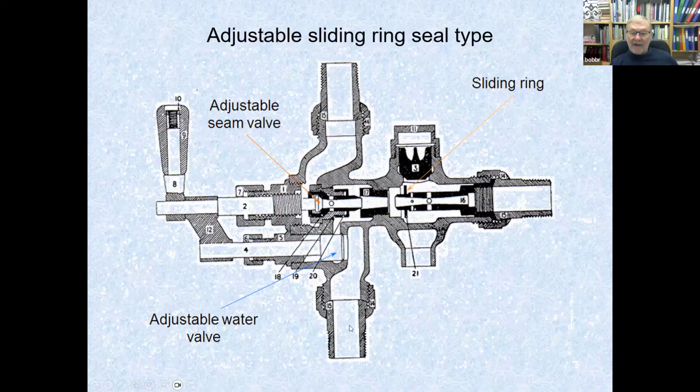So when you're just starting, it limits the water. As I said to you, at low pressures, the water delivery will be less. And as you open this valve, eventually that back collar hits that collar there and pulls this right out and allows more water to feed through the combining cones. It has the sliding ring that slides up to that face there. When there's vacuum in there, it pulls that up onto that ring. If you don't get a vacuum in there, you haven't got an injector that will work.